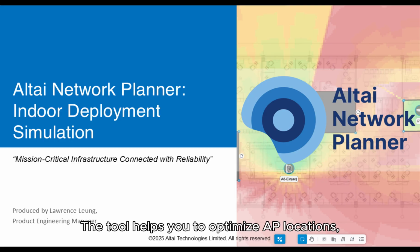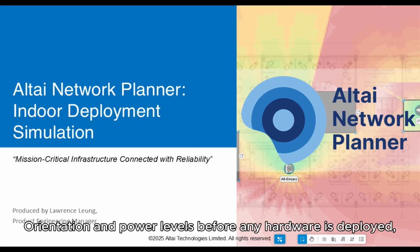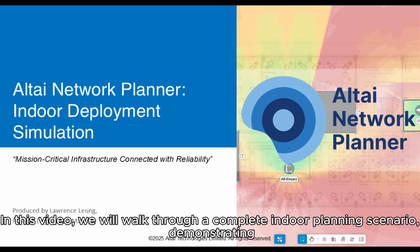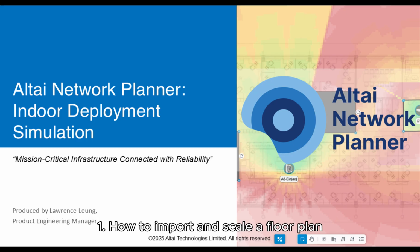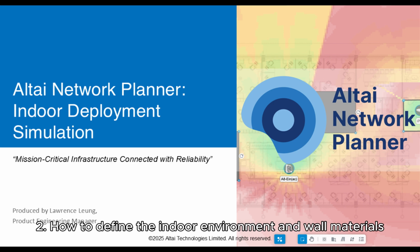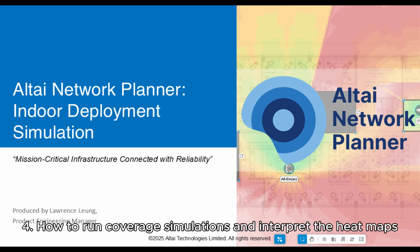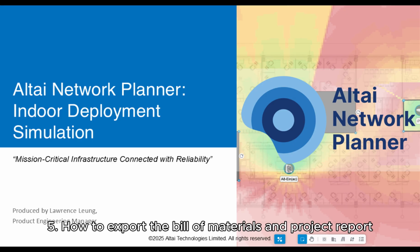The tool helps you to optimize AP locations, orientation, and power levels before any hardware is deployed, saving both design time and installation cost. In this video, we will walk through a complete indoor planning scenario demonstrating: 1. How to import and scale a floor plan. 2. How to define the indoor environment and wall materials. 3. How to place Altai access points and network switches. 4. How to run coverage simulations and interpret the heat maps. 5. How to export the bill of materials and project report.